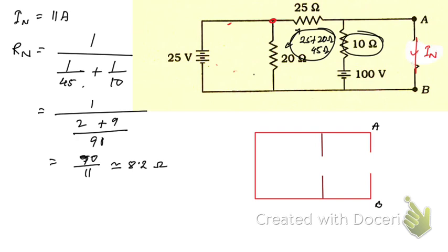What was there was a resistance of 5 ohm, so we have to draw the resistance here. This is the 5 ohm that we used to call the load resistance, right? Here is the Rn that we have got. And the Norton current source is here, this is In. So this is the equivalent Norton circuit.